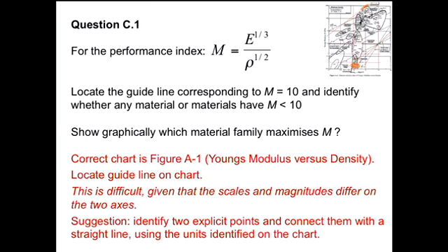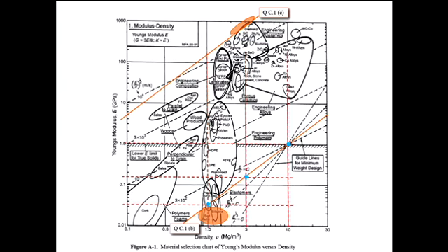The thing down the bottom is what I've said in the past. Different people will have different approaches, but there is no zero intercept in the y equals ax plus c form when we're dealing with log-log equations. So my approach is to choose, say, density equals 1, put it into the equation, and work out the corresponding Young's modulus.